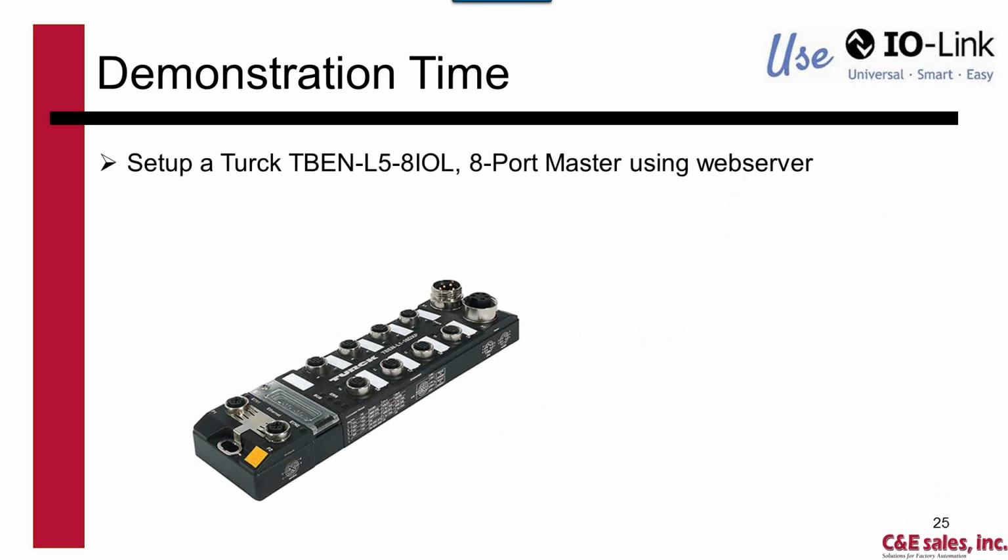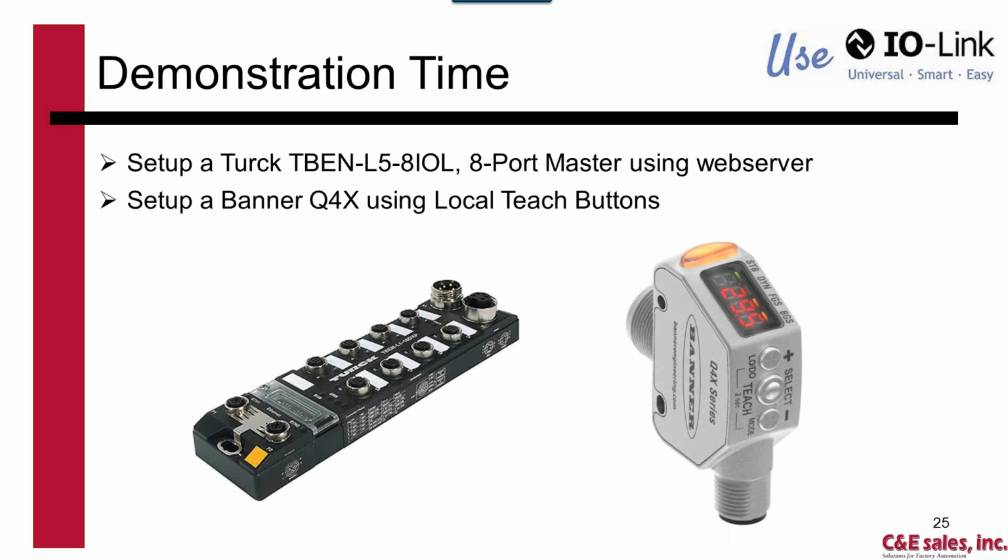It's time for a demonstration. So I'm going to take a Turck TBEN-L5-8-IOL, which is an 8-port master. I'm going to set it up using a web server built into the master. Now we'll take a Banner Q4X. Using the local teach buttons, I'm going to set up the sensor. Now I'm going to show how the simple sensor replacement happens.